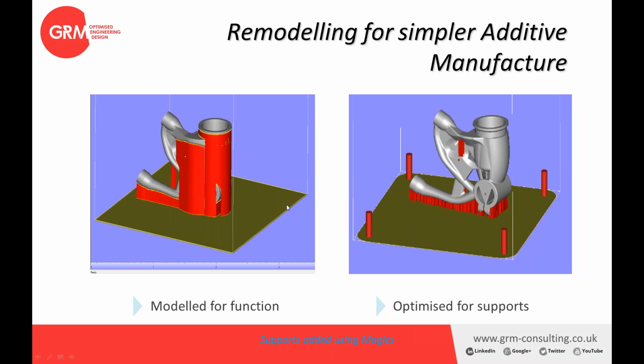So there was a further stage of design and development for additive manufacturing, and one of the key examples is the upper reinforcement section at the top of the part, which you should see with my mouse highlighting, where this was angled, and that angle allows the additive manufacturing process to form that section without the need for additional supports. So that additional process was added in and was proved to be quite enlightening in terms of understanding what is achievable in the additive manufacturing process.